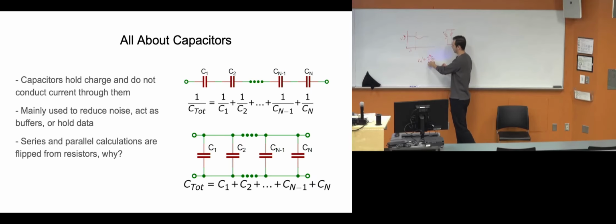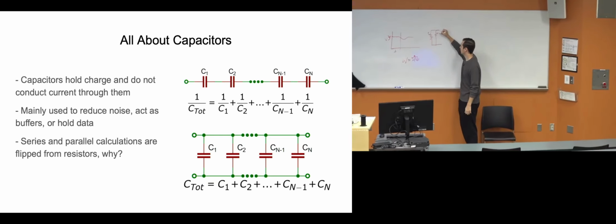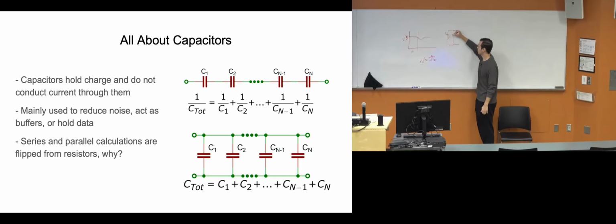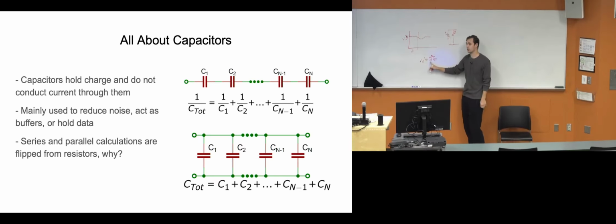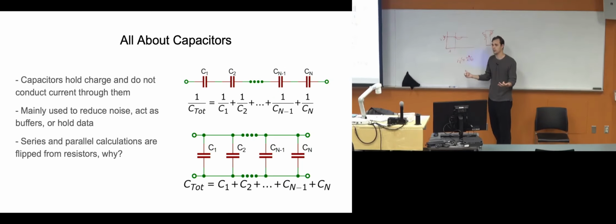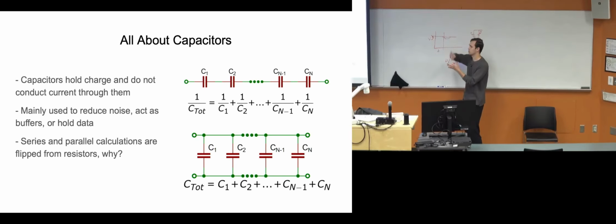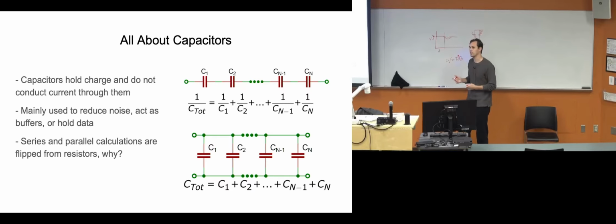When you have a sudden inrush of current and your voltage wants to droop, what's actually going to happen is this charge is going to want to keep this node at 3 volts, right? So it will actually supply charge and supply extra current, which will fight this voltage droop, right? So as you supply more charge, maybe it only droops a little bit, and then your system's good, right? That's the general idea of what capacitors are used for, to eliminate sudden droops or peaks in your system.